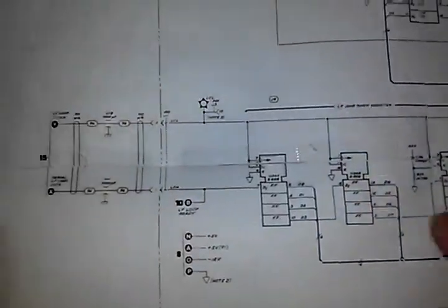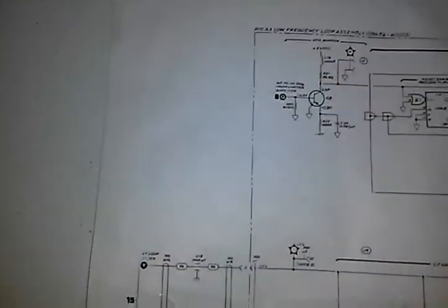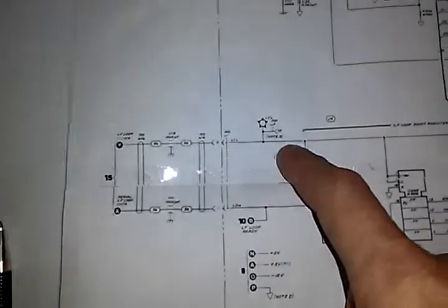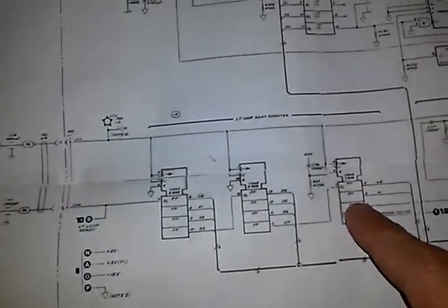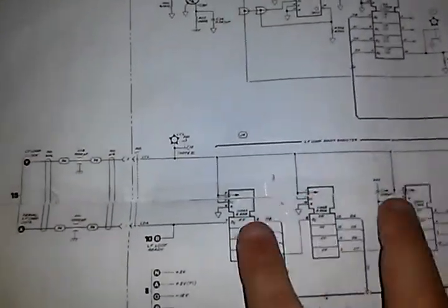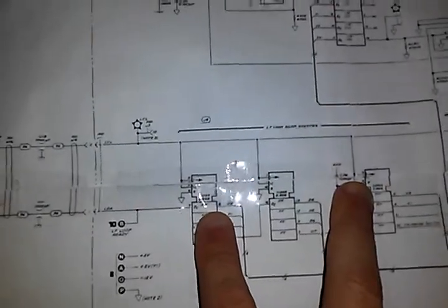This is the schematic of the PLL divide by N timing circuits. And just to go over it real quick, you basically have some shift registers here. This is your clock line, and this is the data line. The data is clocked into these shift registers via this clock and then held on this data bus and distributed through the rest of this circuit.